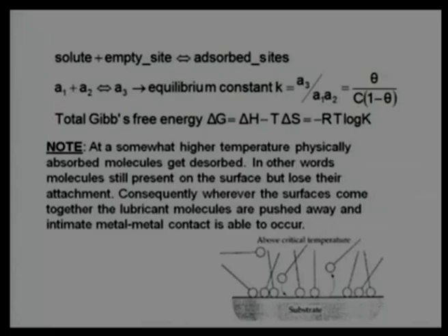Few lubricants work at high temperature, and they do not work at low temperature. You may get a very high coefficient of friction at low temperature, but when you operate those lubricant additives at high temperature, the coefficient of friction will come down. That is generally known as extreme pressure additives, or additives which work with chemical action, or they react with the surface. They make some product, they corrode the surface, they make a sacrificial layer, but they protect the surface or reduce the coefficient of friction compared to dry friction or compared to an unstable film.